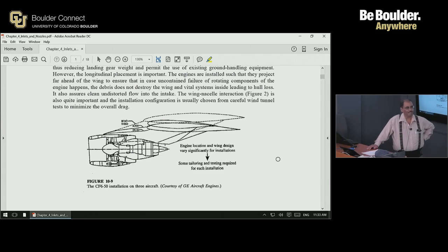Now, the A320 design was, on the other hand, in the 1980s. By that time, moderate bypass ratio engines were the norm, and therefore they designed it with appropriate landing gear length and so on. So now they can accommodate 81-inch fans.